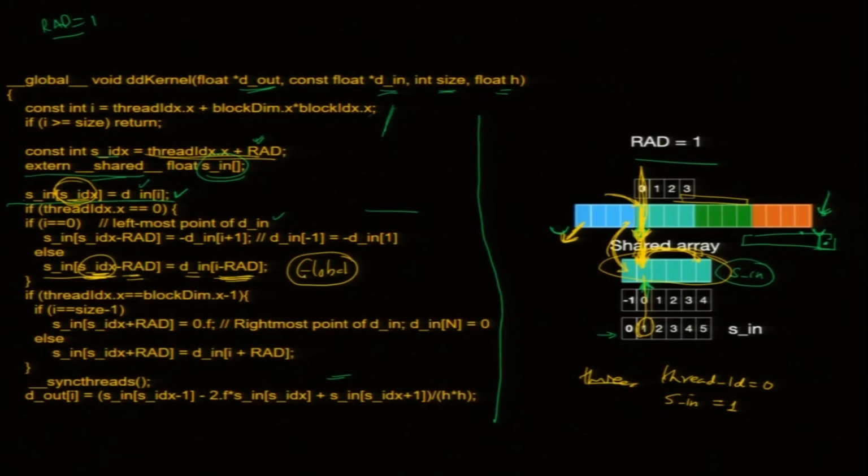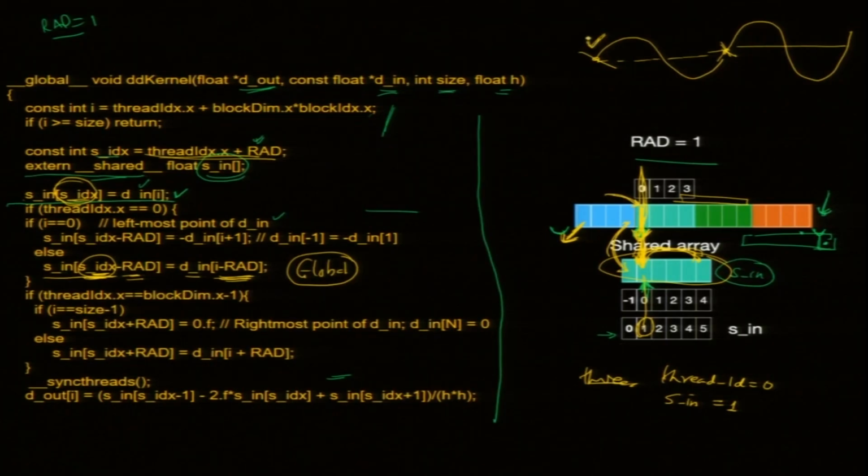My main program uses a sine function. I know it, so for the sine function my data is going like this. By the way, it is also a good idea to keep in mind, in finite difference or any simulation with a periodic box: do not put both the left point and the right point of the periodic box, because the next box will start like this. So this point is repeating. If you are iterating this point, you should not iterate that point, because that can create some ambiguity.